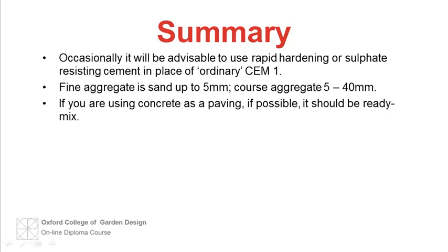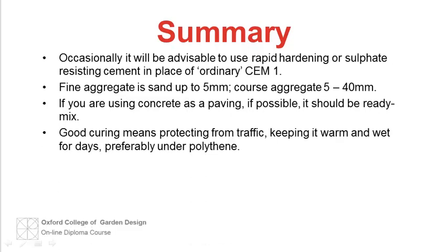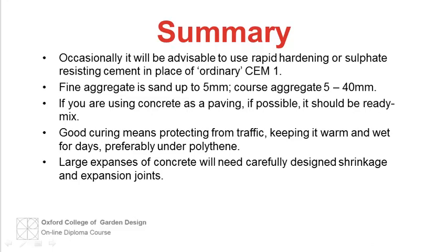If you are using concrete as a paving, it should be ready mixed if possible and well cured, because paving needs durability. Good curing means protecting from early traffic, keeping it warm and wet for days, preferably under polythene. Large expanses of concrete will need careful design shrinkage joints and expansion joints.